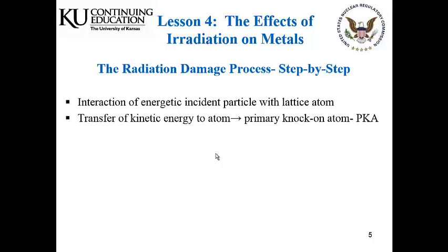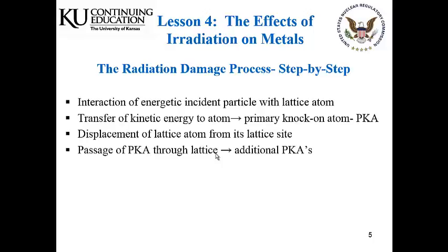It may gain so much energy that it will knock other atoms from the structure. And we'll be looking at the time scale of this as well. And this is basically the displacement of a lattice ion from its normal lattice position. Now, in materials at temperatures above absolute zero, there are missing atoms, voids, in the structure where an atom is missing, and there are interstitials where that atom goes. That occurs just from thermal energy alone. But here we're talking about a much higher incidence of actually knocking atoms free of their normal structure.